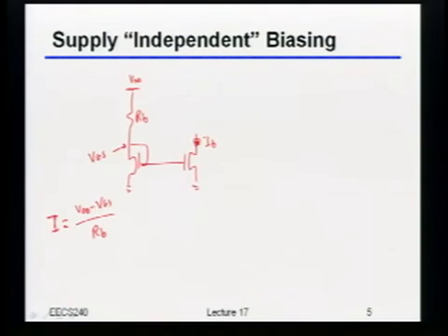Okay, so if we want this thing to be sort of independent of VDD, then what is it that we want to have happen? VGS track VDD? Yeah, basically you want VGS to just track the VDD, right? Well, actually, that would be really good, although unfortunately this particular thing doesn't quite do it.